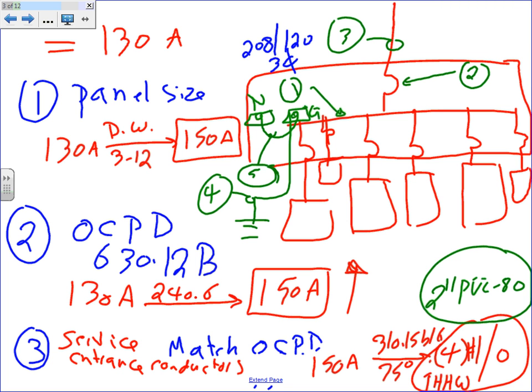Yesterday we were using 40, today we're using 80. Is there some decision-making process? I thought we did 40 for the service yesterday. It's really judgment. At what point would you make the decision? Physical damage. Is the 80 thicker? Yeah, physical damage. That's it. Let me tell you what I can use, no question asked. I'm coming from an underground transformer, underground all the way into the guts of a switchgear. Nothing exposed to any physical damage. That schedule 80 will do it.